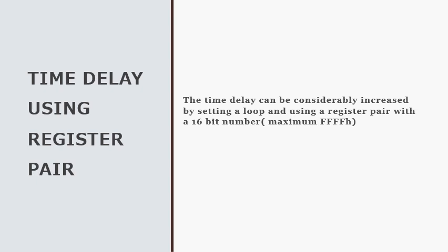The 16-bit number is decremented by using the instruction DCX, right? We can decrement it, isn't it? However, the instruction DCX does not set the 0 flag, and without testing the flag, a jump instruction cannot jump to a desired condition, right? An additional technique we must therefore use to set the 0 flag is the OR instruction.